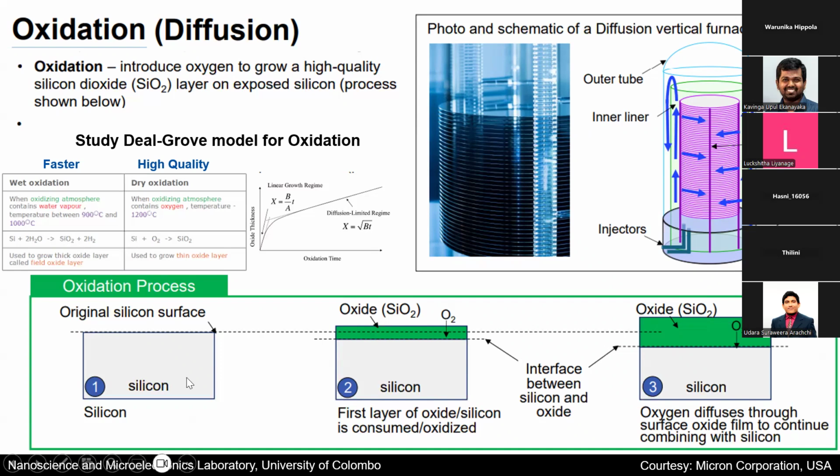So let's say you have silicon, this is the wafer surface, and oxygen is flowing over when it is really hot. Then the oxide is formed and the oxide thickness gets larger and larger. The oxygen molecules come in at the top, they have to diffuse through this silicon dioxide, and then they move on to the silicon, react, and form the oxide at the interface, right?